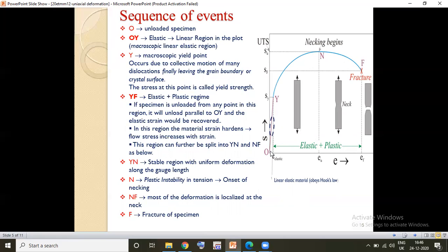You can see that within the elastic region, the curve is linear, and the curve deviates from its linearity beyond the point known as the proportional limit. After that, we have a point known as the elastic limit, where beyond this point, if you load further, it will convert into the plastic region where permanent deformation is taking place. Then we have the yield point, where the permanent deformation can be seen in the material.